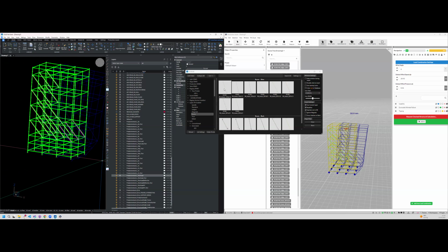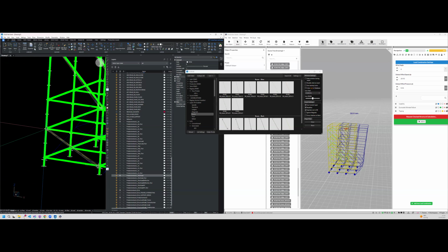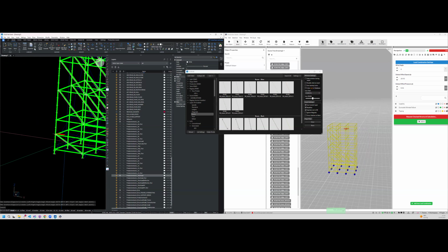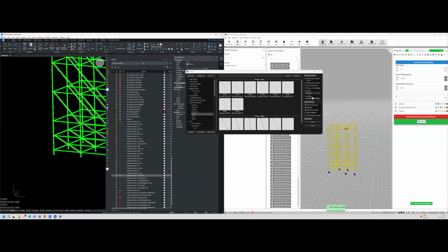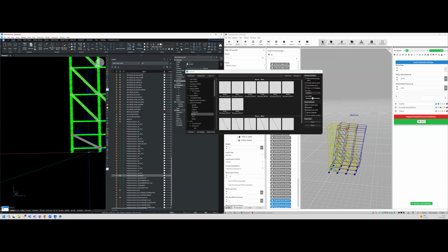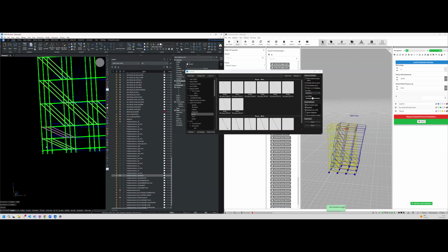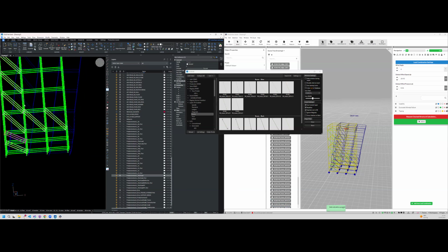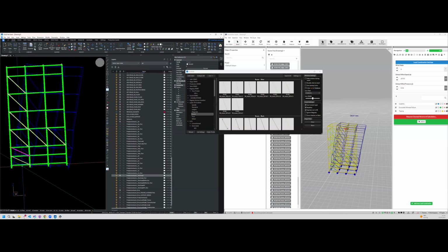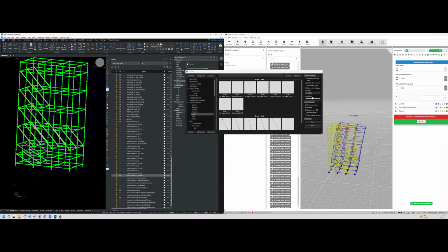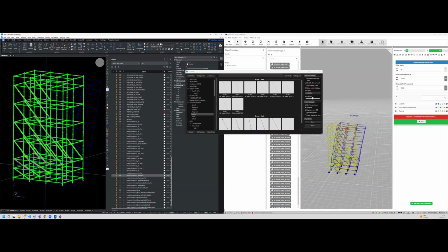So for this, I go into the brace 207 1 meter and add this in here, and then copy it 1, 2, 3, and also moving it CZ up by 1 meter, enter, and copying it. Now I have it like this. Now see, it's not that big anymore. So this really allows you to put in the diagonals only where you need them so that you have a proper reinforcing layer construction that you can use for the calculation.